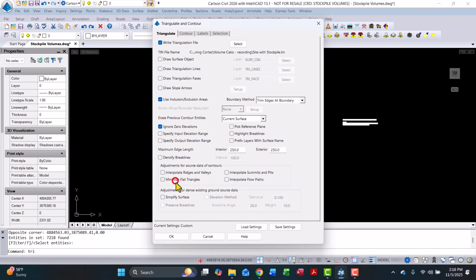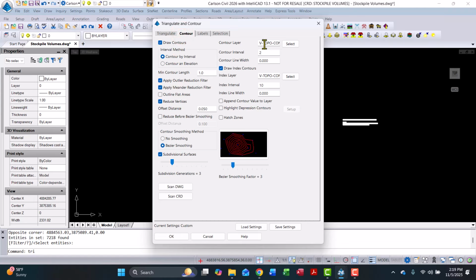And again, you notice we use that survey by grid to do a good resolution for the stockpile, and then we didn't need that many points for the rest of the site. All right, so I'm going to finish up here with layer names. I'm just trying to be consistent here so we're not overwriting things here and there. So we'll have separate layers. That is good.